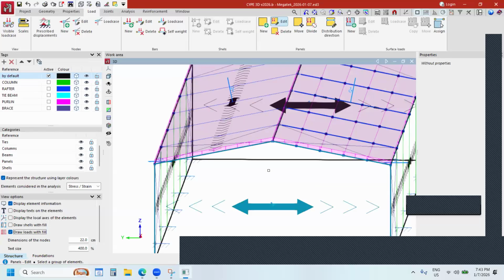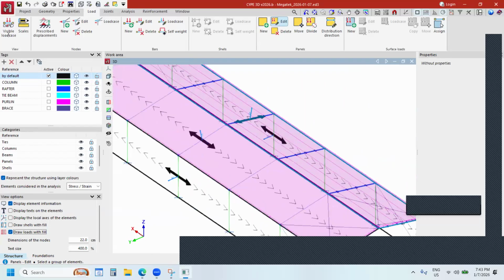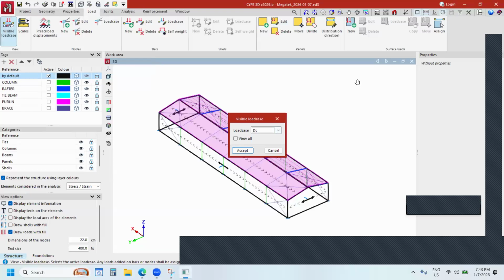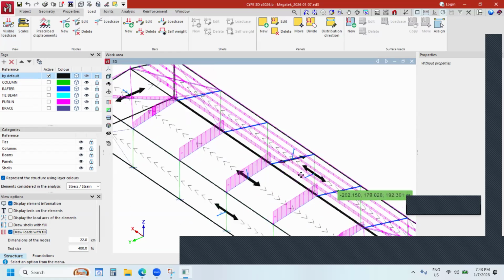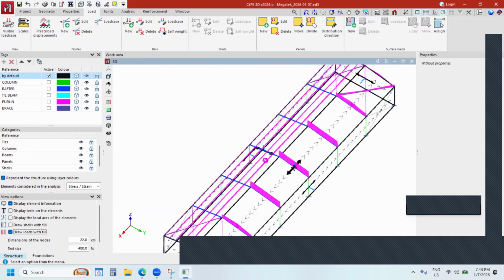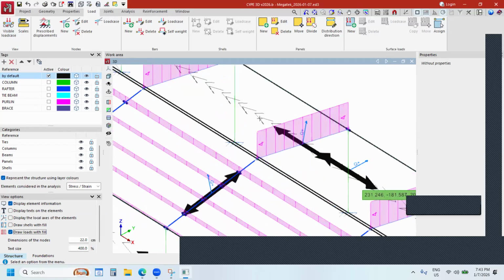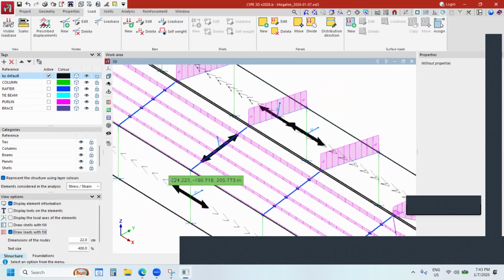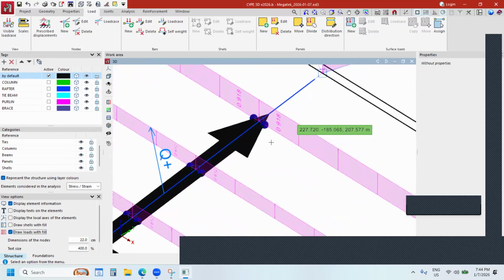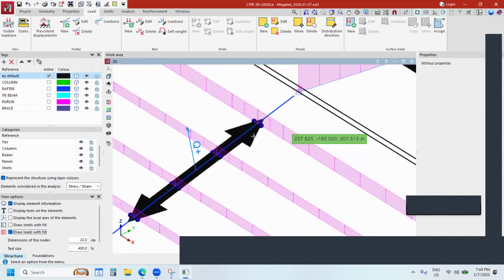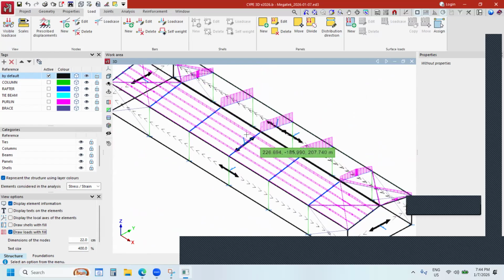If you want to look at the load on the member, again you can go to visible load case. You see here I have the dead load. Let me look at the dead load, and you see how the loads are applied to the rafter for this one. If you look at the distribution direction of the load, and then here the purlins are loaded, and you can see the value of the load. I applied the pressure, but the software automatically decomposes it to member load.